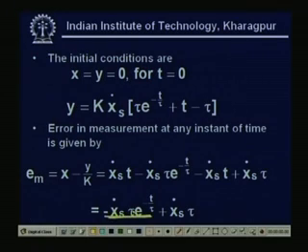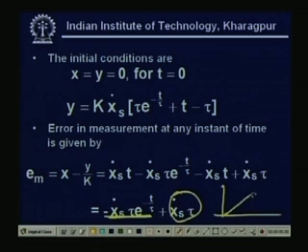So, this will become almost 0 for some value, and as the time grows, this will become insignificant, and the other will be predominant. That is the reason we got the characteristics like this. This is my output and this is my input. So, error initially is very small and as the time goes we have a steady state error, which is x_s dot into tau.